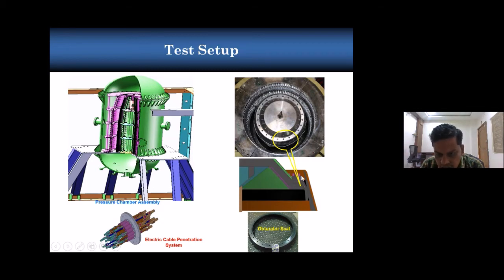It's called the actuator seal. Then there is a retainer ring. Whenever this is pressurized, this rubber seal will get intact with the F1 section. It will hold the pressure there. Here one more constraint is that the axial force coming onto the lid should not be transferred to the airframe section. That is the main constraint. That's why we have to make a rubber contact between this metal and metal section.